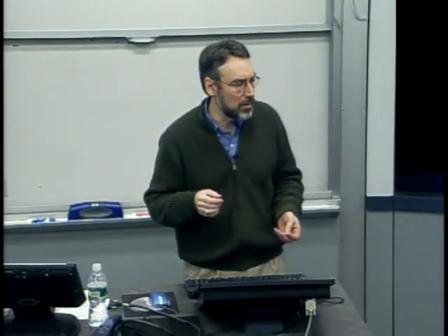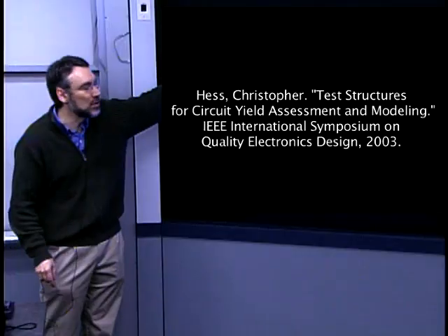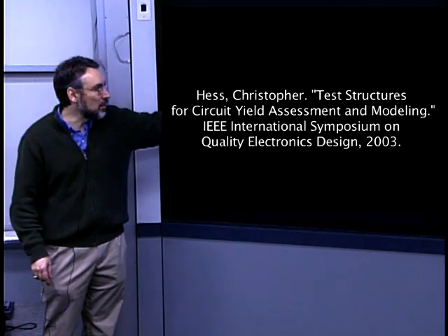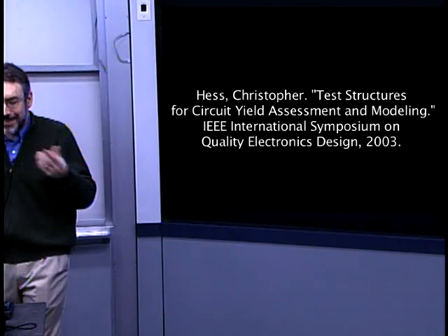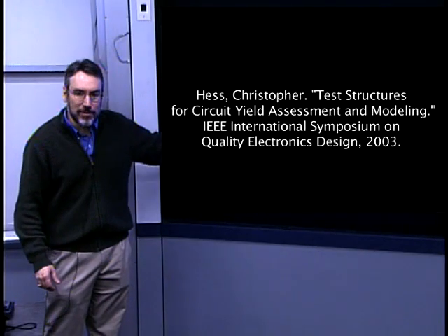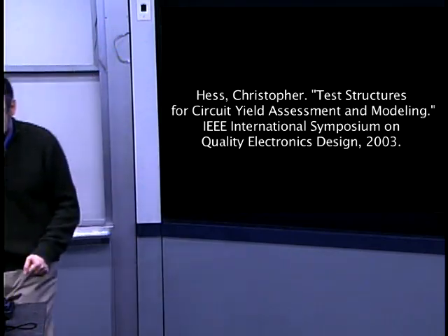Okay, and we'll talk about that, I think, somewhere near the midpoint or second, last third of the course. We'll talk about yield modeling and some of the technologies that are used for characterizing statistically the point defects, particle defects, and some of the strategies used for optimizing or minimizing the impact on circuits.